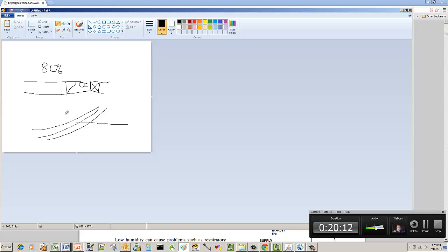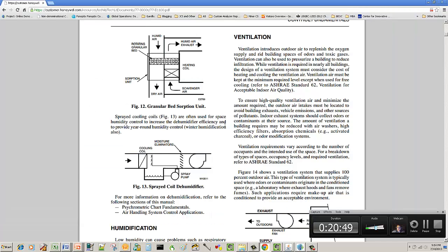which means that as the air cools down, the molecules slow down, there's less room in the air to hold the water, and that water is essentially going to fall out into the condensate drain, because we call water that's falling off of a coil condensate because it's condensing. The water in the air is condensing, so it's condensate, and it runs down the drain, and humidity leaves the air. We warm the air back up, and lo and behold, we're at a lower humidity point. This will make complete sense when we move through the psych chart, but you're just going to have to trust me on it right now.